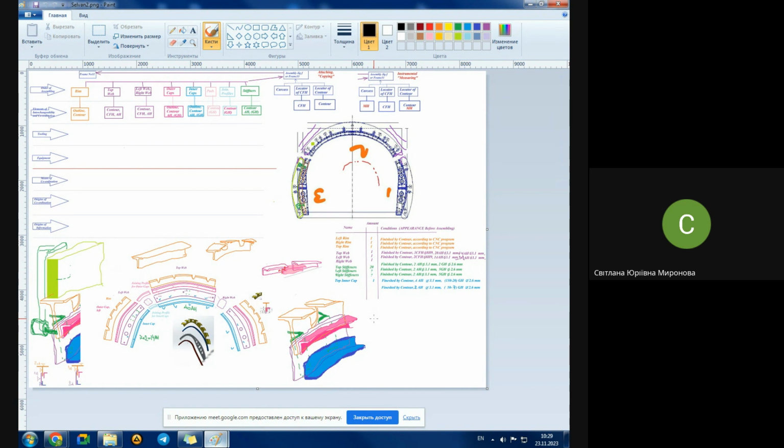Either we use special means of coordination, special means for mounting the jig. Special means repeating the sizes and shapes of assembly units. In this case, we use the technique of attaching elements of the jig to a physical carrier of sizes, some imitation of the real assembly unit. This imitator may be flat, then it's called a template, or three-dimensional, then it's called a mounting standard, or mock-up.